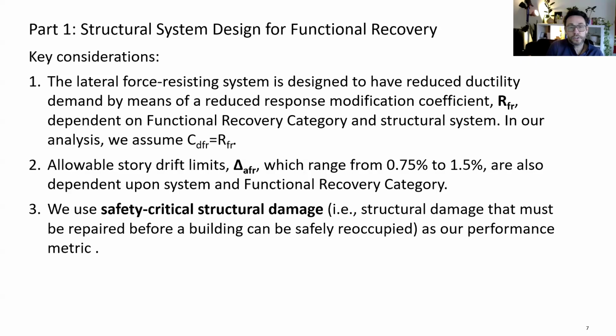We consider damage to structural components only when we're exploring appropriate values of RFR and drift limits, and we use safety critical structural damage as our building level performance metric. Safety critical structural damage is structural damage that must be repaired before a building can be reoccupied. And the key idea here is that a structure that is deemed safe is essentially a first requirement for recovery. And also that safety critical structural damage is essentially a proxy for very lengthy recovery times, which is exactly what we're trying to avoid with these provisions.